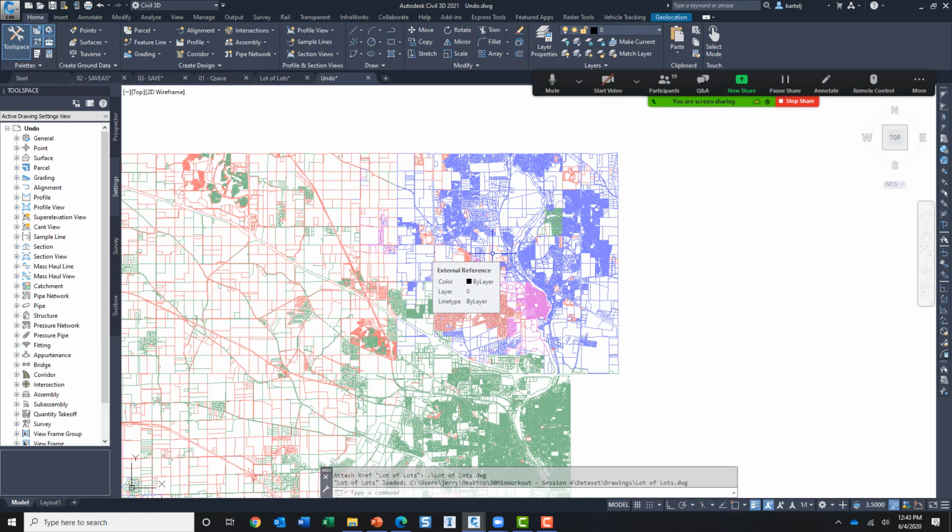Now I like to do circular type shapes. Sometimes that makes nice looking details, so we won't do a rectangle. I can't use a circle in a clip. So what I'm going to do is make a polygon of maybe 50 sides, because if I create a polygon of 50 sides, it really starts to look like a circle anyway. So we'll go ahead and create that. That's going to be the limits of my clip, the area that I would like to see.